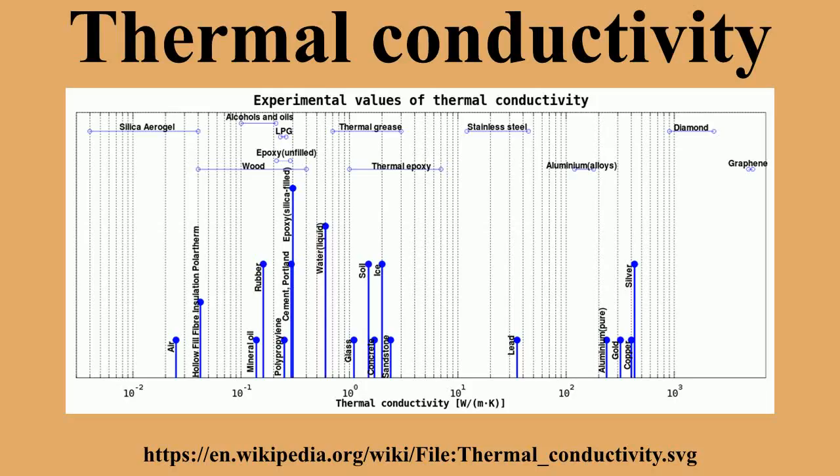Thermal anisotropy. Some substances, such as non-cubic crystals, can exhibit different thermal conductivities along different crystal axes, due to differences in phonon coupling along a given crystal axis. Sapphire is a notable example of variable thermal conductivity based on orientation and temperature, with 35 W/m·K along the C-axis and 32 W/m·K along the A-axis. Wood generally conducts better along the grain than across it. When anisotropy is present, the direction of heat flow may not be exactly the same as the direction of the